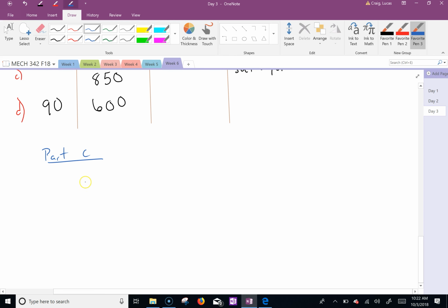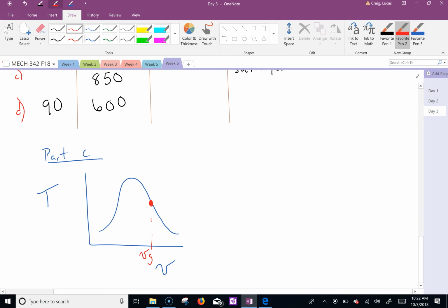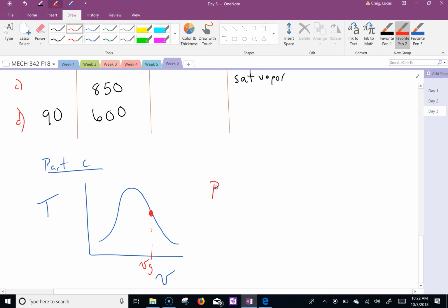Again, I like to do TV. You can do PV, whatever you want. We know we are saturated vapor. We're here, so we're VG. We know the pressure is 850 kilopascals. We know that V is VG.